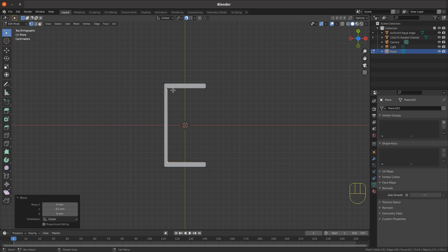Now the problem we've got if we rotate these two flanges 5 degrees is it moves, because it's rotating it, it's moving the two inner and outer vertex out of position, so they're no longer parallel with where the back web should be or where the toe of the channel is. So we need to now separate the two edges so we can move them separate from the web and the filler edges that fill the front of the flanges.